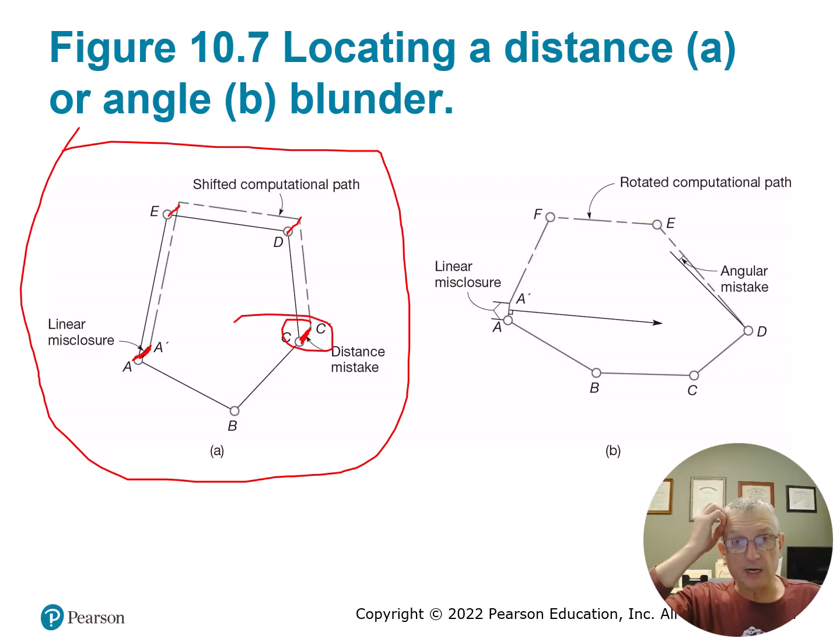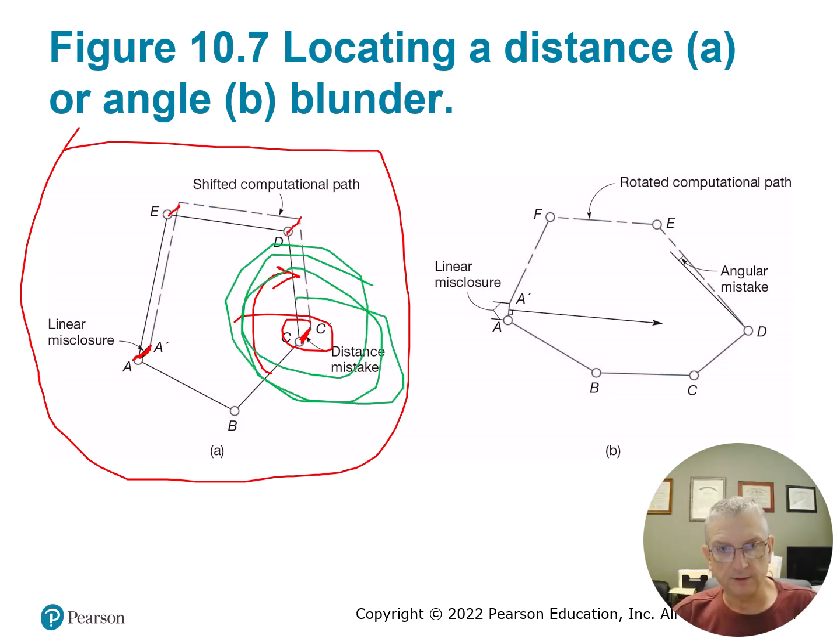So you might run it up and say, wow, we've got a bust. Dang, we're out 7 feet. That's not good. What did we do? And you might figure out, okay, well, the bearing of the error is really close to the bearing from B to C. And if your angles measure good, because your angles were measured in here at B to D, so your angles were measured correctly, this is the only error in this example, this error made from C to C prime.